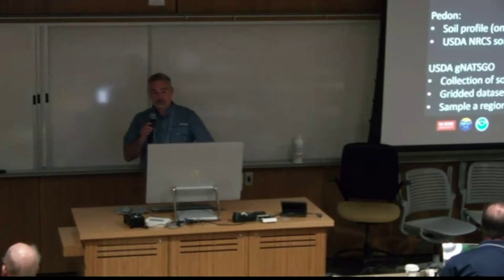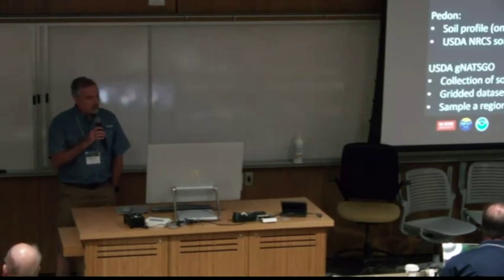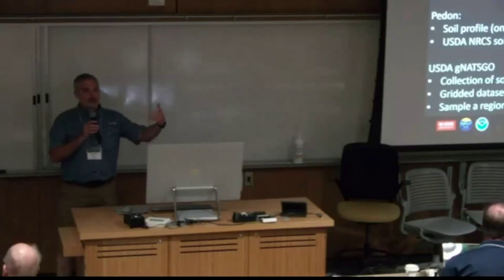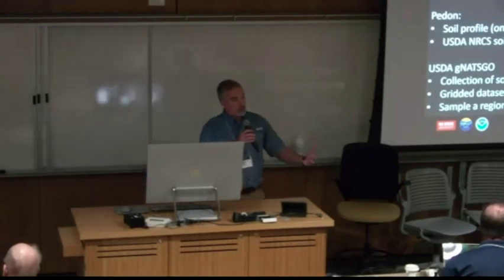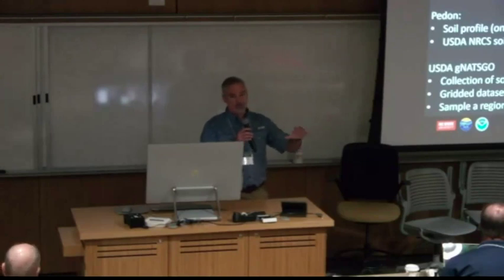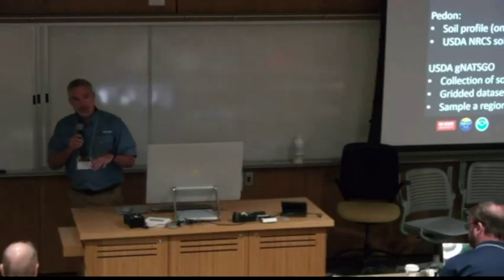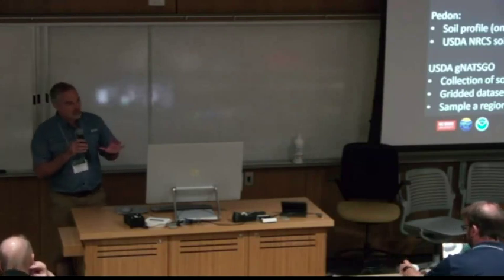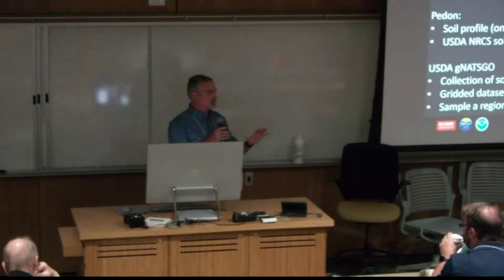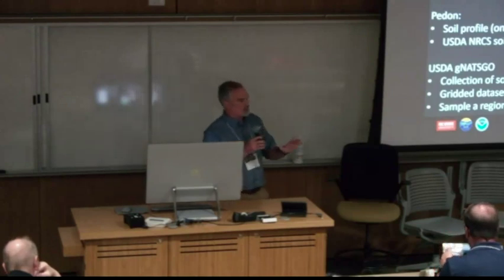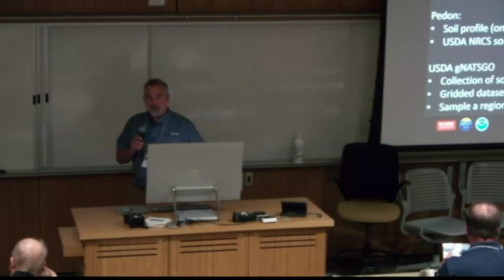Okay, so where can you get soil metadata or these wilting point and field capacity conditions? Traditionally, you might go out when you're putting the soils in and take a soil sample. You might go in afterwards and take a couple more soil samples, and you can send these to a lab, or if you have machines, you can compute these values based on your soil samples. If you're like CRN, we have about 114 stations, and we only have about 58 of them where we got lab results back. So I only have pedon results for about 58 stations.